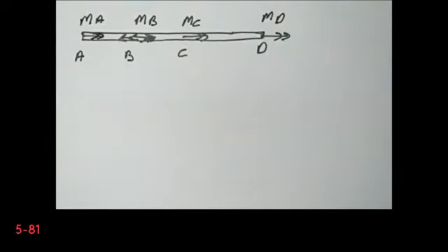In fact, I don't know the values of MA and MD. I have two unknowns and I have only one equation. Therefore, I cannot solve the problem just by using static equilibrium. I need an additional equation, and that comes from the rotation of the shaft.